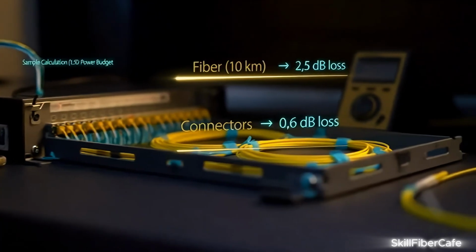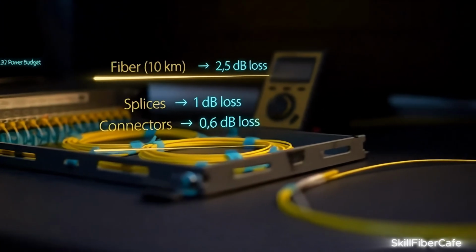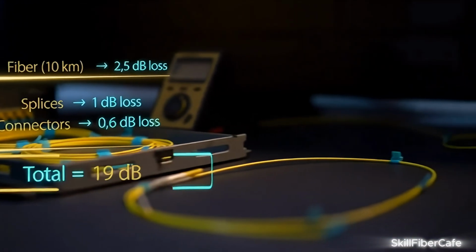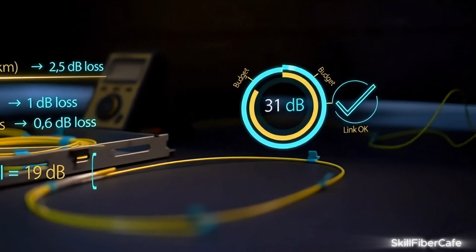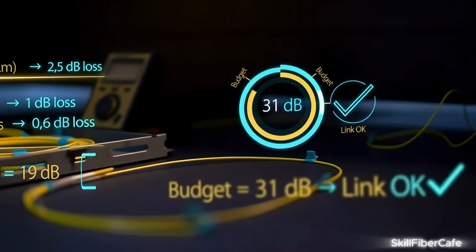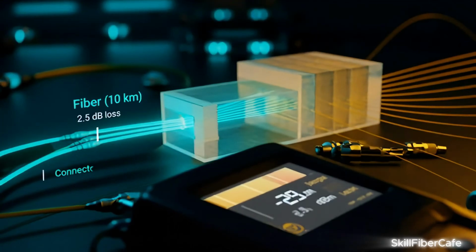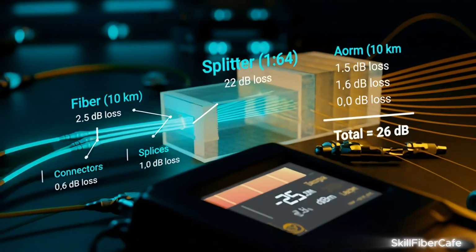Example: 10 kilometers of fiber adds 0.5 decibels of loss, connectors 0.6, splices 1, and a splitter 15 decibels, for a total of around 19 decibels. With a 31 decibel budget, the link runs perfectly. Any extra loss still keeps margin for safety. Doubling the split doubles endpoints but raises loss to nearly 22 decibels. Still functional, but system margin becomes tight.